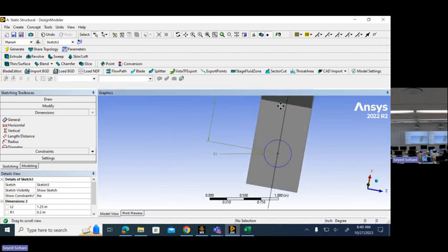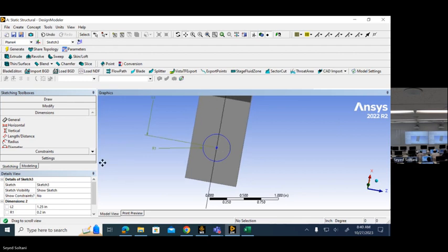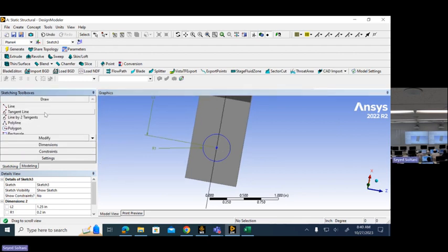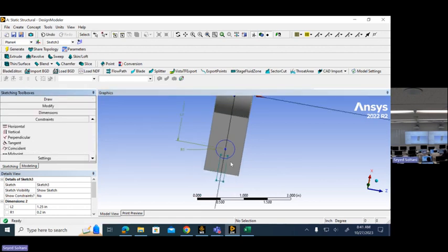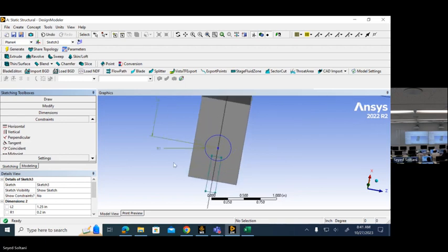Okay, so now as far as the other feature, I need to add a rectangle. So I roughly place it here, but then I add the constraints. So once the symmetry constraint, then it should be symmetric with respect to this axis, whatever that is, x. Then I just need to add the dimension.